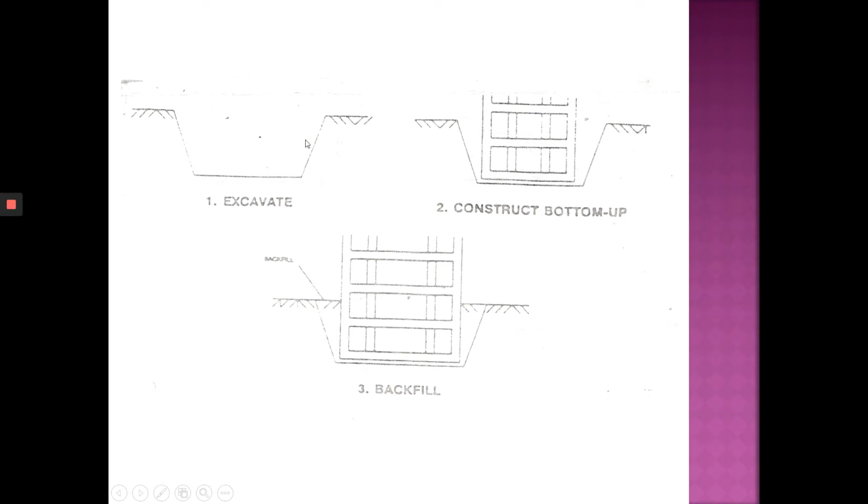So the first thing you excavate, okay, and the degree here, it depends, right? And then you construct as normal. You will have the slab, and then you will have the wall of the basement. Okay, nampak tak ruang ni? This space, okay, you have these spaces at the sides. These spaces need to be backfilled. You tutup balik, backfilled again with the soil, with the excavated soil. Normally, that's what they do.